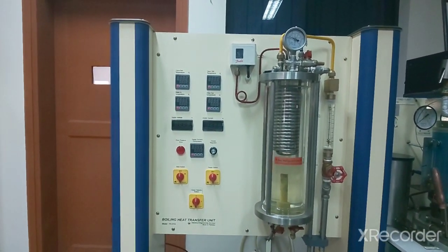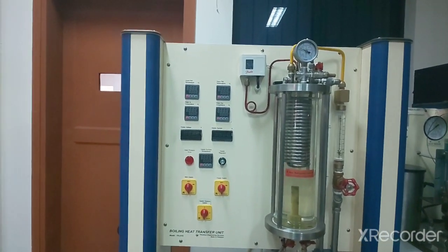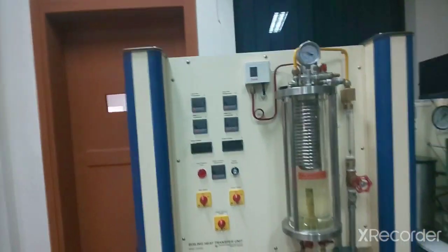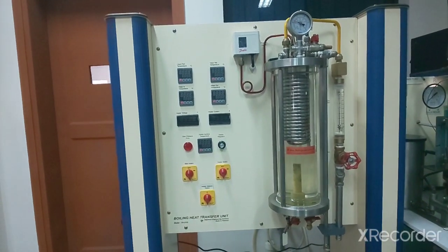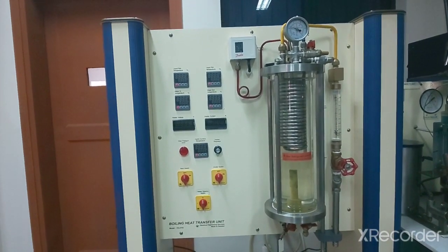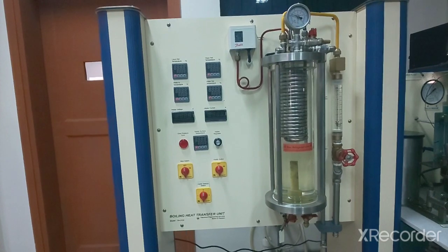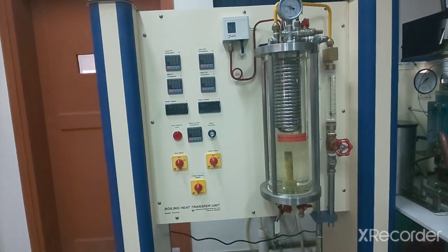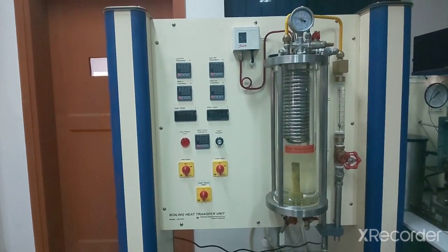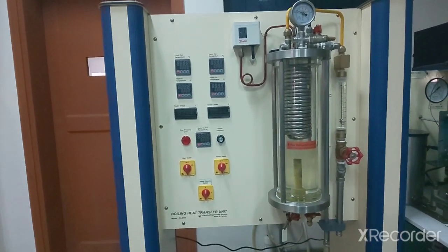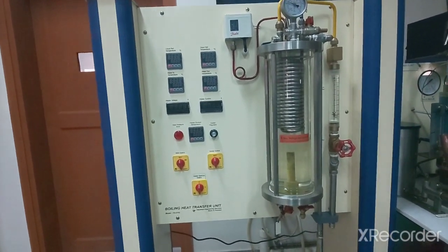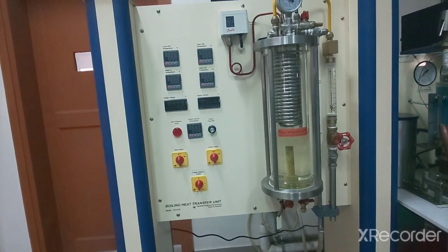Boiling regimes are introduced when there is a difference between the temperature of the boiling liquid and the boiling surface, the heat transferring or heat providing surface, whatever you want to call it. The temperature of the surface through which the heat is coming into the liquid has to be higher, so that the heat will shift from the surface to the liquid. So how much higher? That is the question.